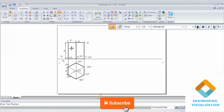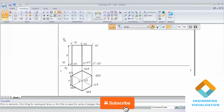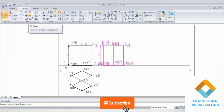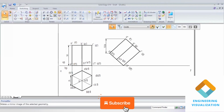Now we need to copy the same diagram using the move command and incline it with the base edge, since the inclination to the base edge is given. Actually they give the angle of inclination to the axis, but we incline with the base edge, as it is easier to do the inclination. So use the move command, create a copy, slide along the XY line, go to rotate and take the base edge. The inclination is 45 degrees, so incline it by 45, and it has been inclined.